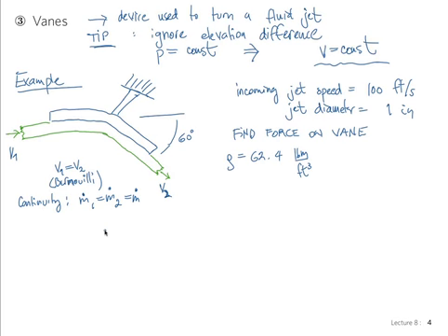So let's choose a control volume wisely, and the wisest way is to be always perpendicular to the velocity, at both places. In the middle, it doesn't really matter because the velocity is 0, so in between here we don't care. But the surfaces at the entrance and the exit of the control volume are perpendicular to the velocity.